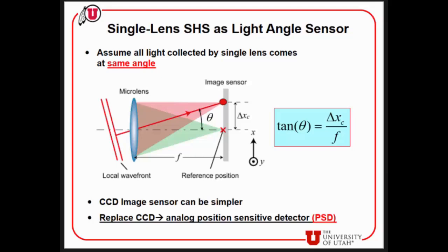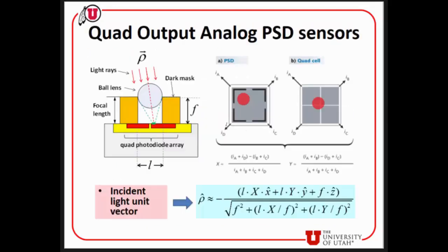Now, the advantage of the SHS sensors is that they use all of the incoming light rays to form a signal, which is the main difference. Whereas the previous ones, as I showed, use the shadow concept, in this case I have a lot more electrical output, a lot more electrical photocurrent, which means I can even track in low light conditions, and also track objects which are not that reflective, not that bright in nature.